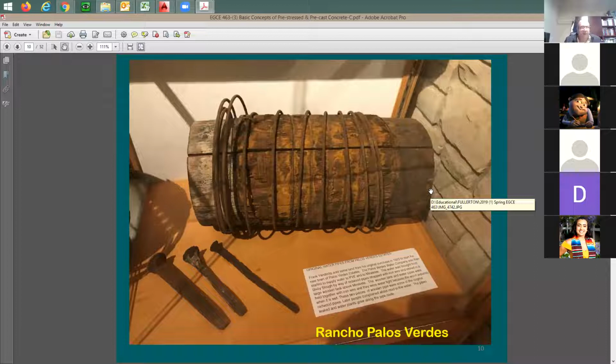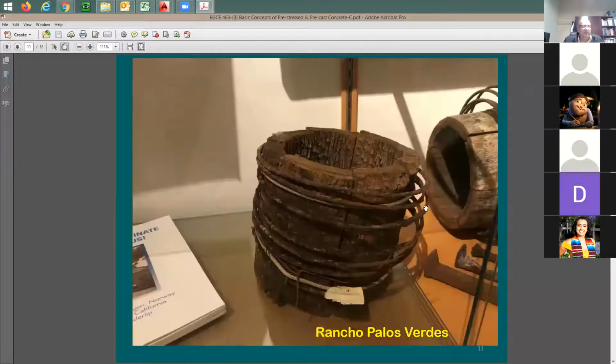When you pull the wire, you put tension on the wire itself. And of course, one side's gonna get anchored. So here you're gonna anchor the wire to the pipe itself, and then you're gonna start to run it around it. And then at the end, you're gonna apply some tension. During this process, you're gonna apply lots of tension on the wire itself. Now the tension is gonna be in the wire, but the body itself of the pipe is gonna be exposed to high compressive stresses. This is why we call it pre-stress. So actually this pre-stress is nothing new. This has been there forever.